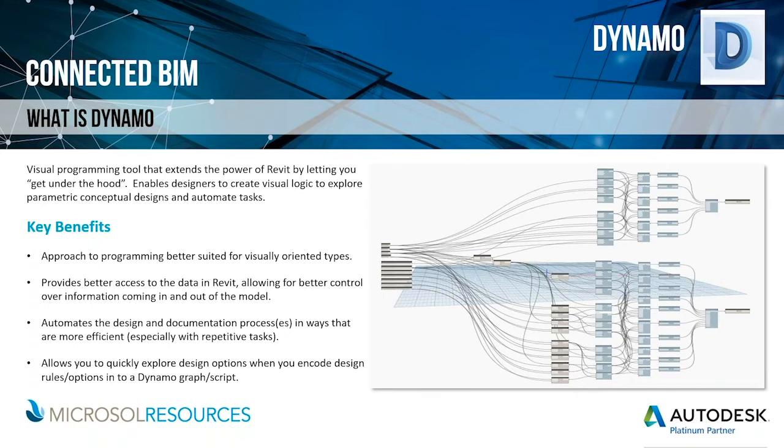Fortunately, there are a number of ways to automate Revit, two of the most popular being Dynamo and Revit macros. Both are programming-based, but the difference is that macros are text-based programs, which typically involve understanding a programming language, whereas Dynamo is more of a visual programming tool and thus more accessible to those of us with that type of mindset.